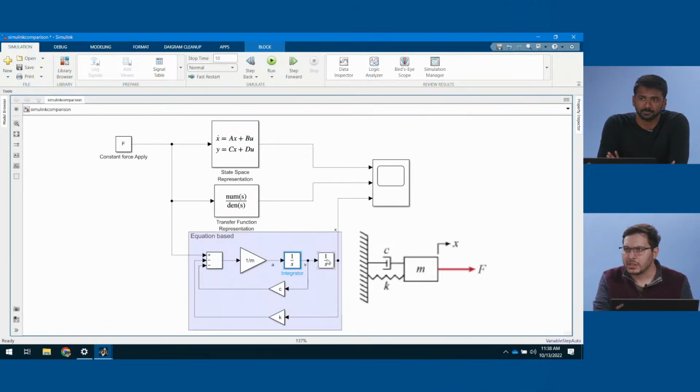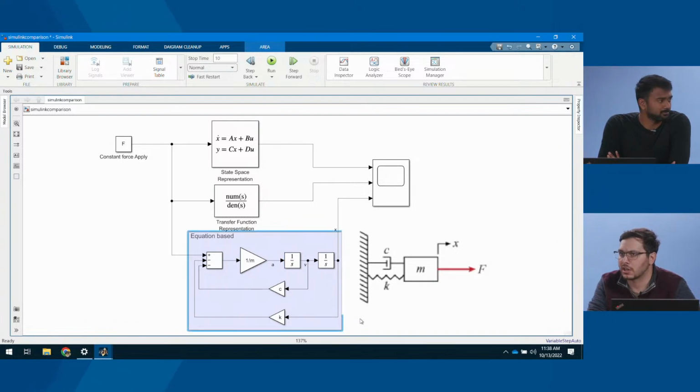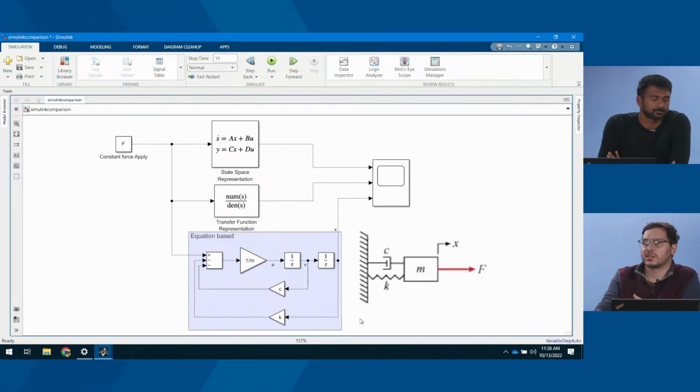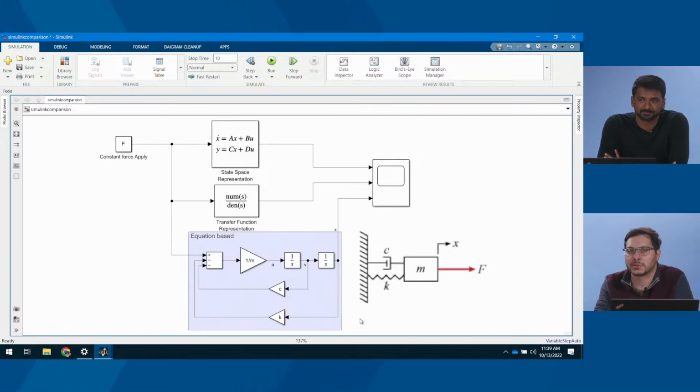That makes sense. But this is something that can happen when you're working with Simulink and you're looping back values like this: you can get what's called an algebraic loop, where Simulink isn't able to solve this system of equations for you. There are some good documentation pages on how to solve algebraic loops. It's especially likely as you throw together different models you've made of different components, and you're just not thinking, it's 11 o'clock, you've got an exam the next morning. It's something that can happen, and there's good documentation on how to resolve those.